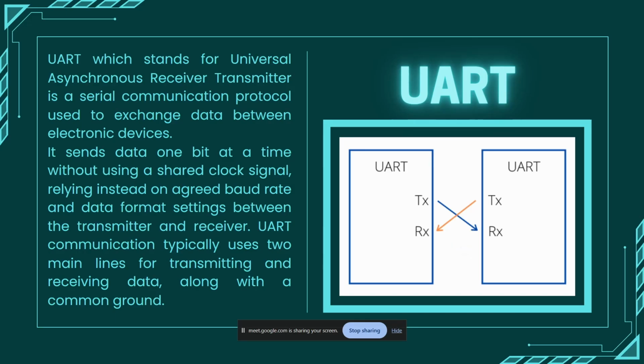So yeah, UART is duplex, like I explained. We have a two-lane highway where traffic is moving in both directions simultaneously. And there is no clock. So there is the word asynchronous. Asynchronous means that there is no clock signal. It's just that both units know at what frequency we are transmitting data.